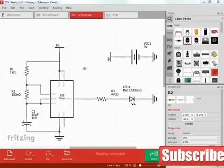We can see that everything in the circuit that's marked 9 volts, although it's not physically connected on the drawing, is electrically connected. And also with all the ground connections. We have 2 9-volt connections and 3 ground connections. This is a way that we can clean up our schematics without having lines drawing all over the place. We just put symbols for common connections and we assume that they are all connected electrically.